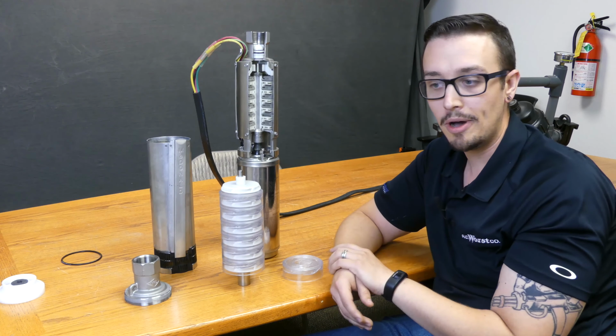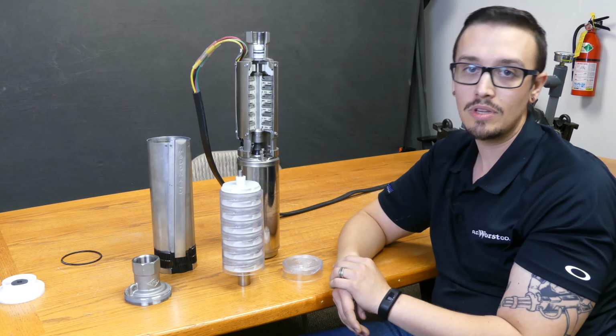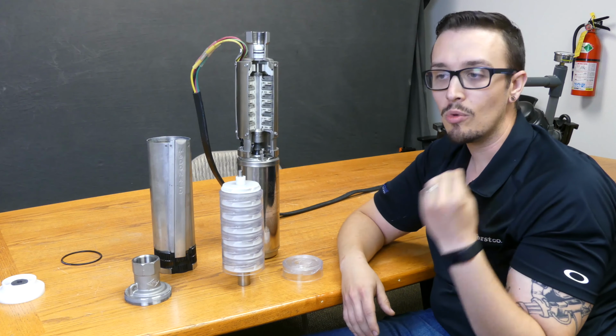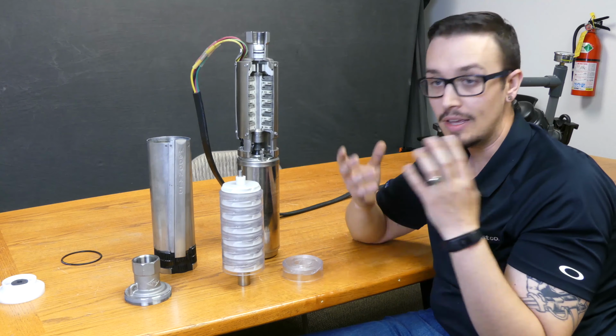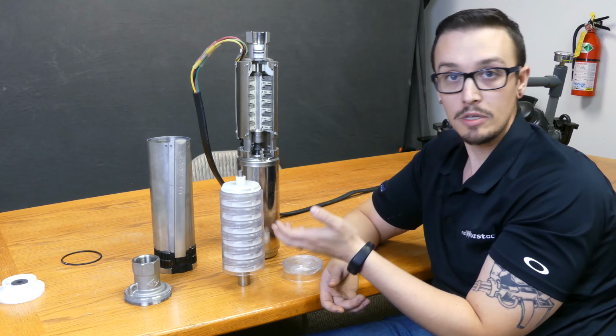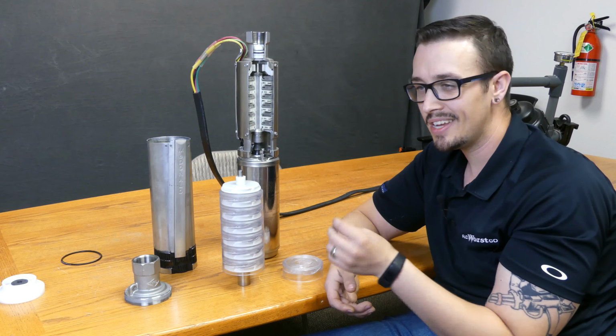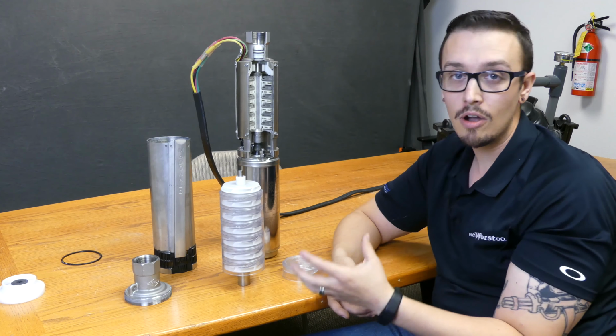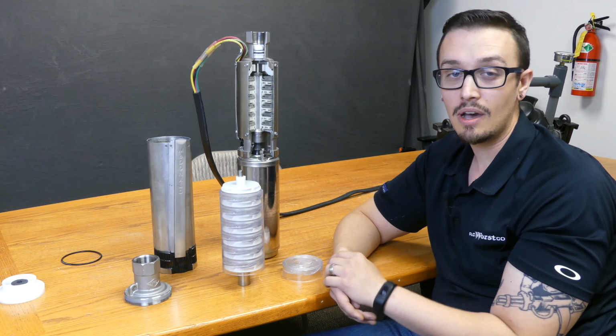So I think this pump design is absolutely ingenious, and I'm not saying that you need to go with the stainless steel pump, because I find that those pumps in particular aren't able to handle sand as well, and they're more likely to get bound up. And if it gets bound up, you're looking at a burnt motor. If this pump passes the sand through it and takes a hint of wear along the way, that's much better in the long run when you're talking about the replacement costs of setting a new well.